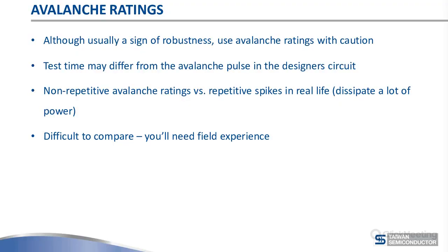Another thing that I wouldn't compare, or the one I am most worried about or not convinced about, is avalanche ratings in rectifier datasheets. They are a sign of robustness, so there's nothing wrong with them. If you use avalanche testing, then you weed out some parts with poor characteristics. So there's nothing theoretically wrong with that parameter.